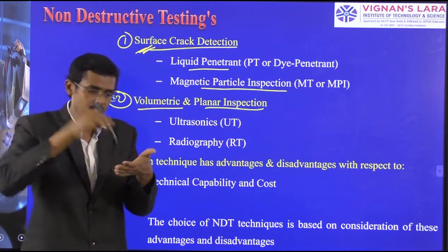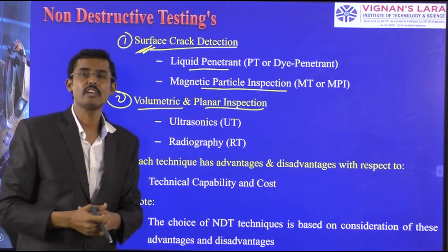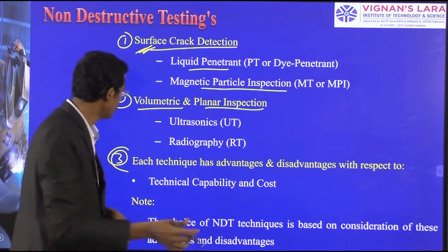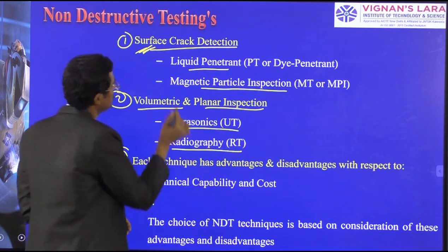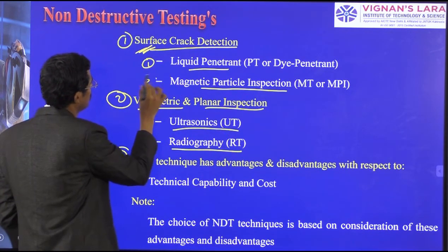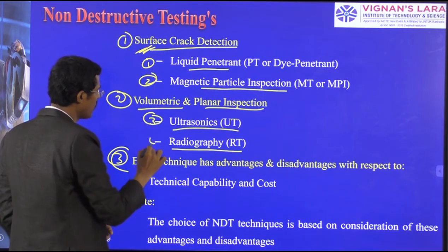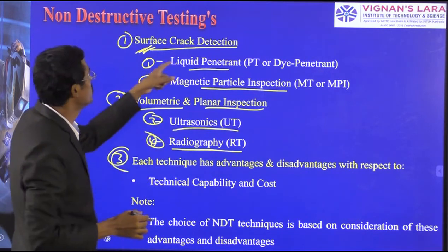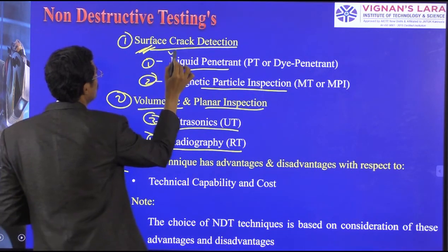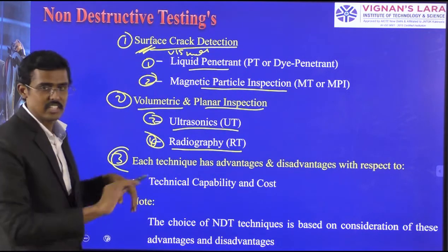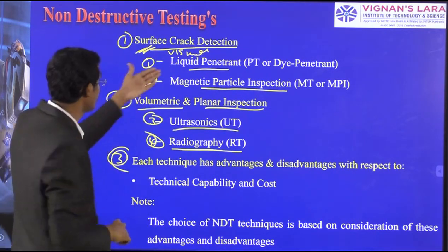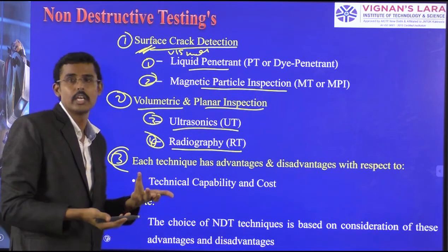Then which methods will find the inside, volumetric, inner defects? Therefore we are using radiography and ultrasonic. So you see here 1, 2, 3, 4 come here. Additionally, visual inspections are also possible here for the surface defects. So after liquid penetration we should look, that is visual inspection.